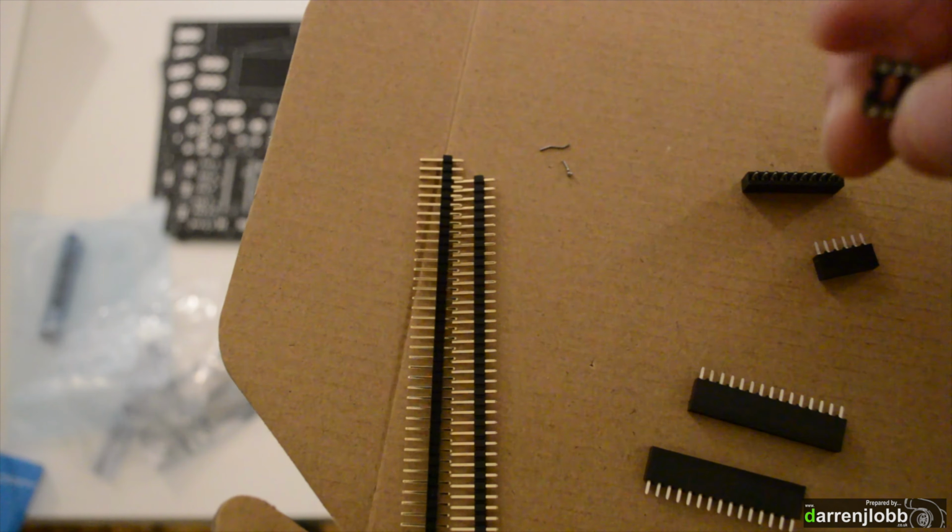If you look on the board now, we've got it marked just above those three big caps. So you can see there we marked LED. The positive side is the side towards the resistor, it's fed from there. So you've got your long leg on this side and your short leg on that side. I'll just solder that one in a minute.